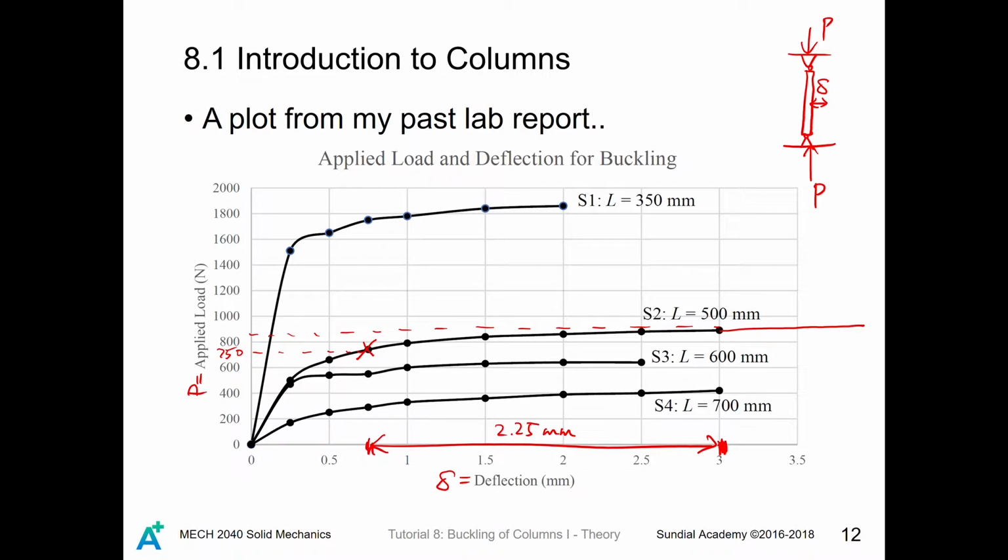So as you can see from this plot, the deflection is actually a kind of stability problem. That is, once your applied load is less than some critical value, then your column can withstand normally. But if you apply a super large load for this specimen, I believe this column will suddenly be destroyed.